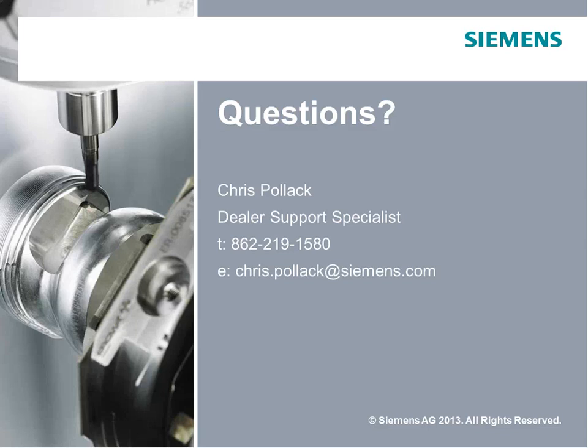Here's a question. Was it a different post-processor I used for this as opposed to their 840 control? I did mention that earlier as well, but let's briefly talk about that. It was the same post-processor. Certainly some of the critical things that we were talking about were really just those slight machine differences. Be careful, but no, the core code was really the same between the 808 and the 840. Certainly, some of the differences is the ShopMill type protocol that you get in the higher controls.